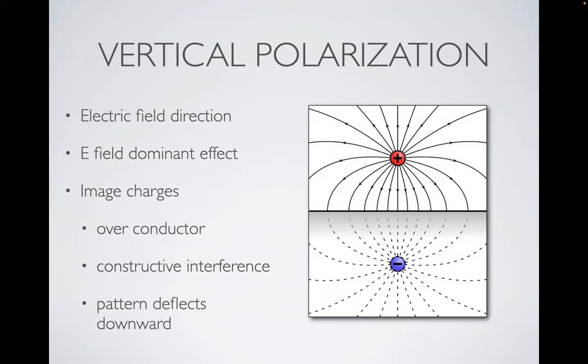And if you have a better conducting surface, like you've heard about the salt water effect, as you get close to the salt water, you get better image charge effects. And that tends to, by constructive and destructive interference, pull that pattern down. So that's the consideration about what you want out of the pattern. If you're trying to do NVIS, this is probably not a good plan to keep it low. But on the other hand, if you were doing horizontal on NVIS, it tends to work.